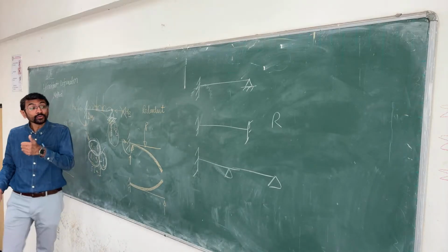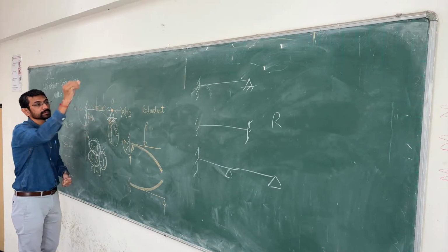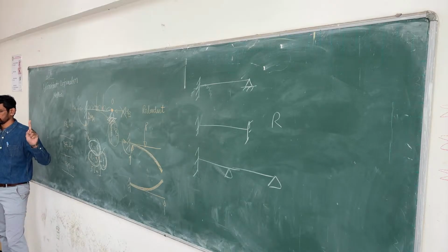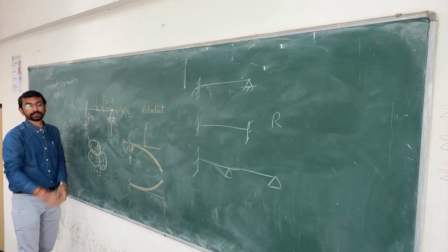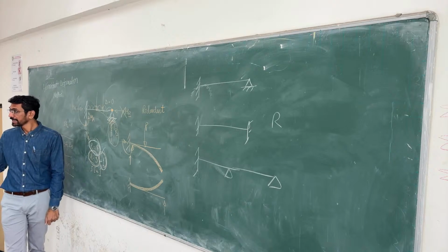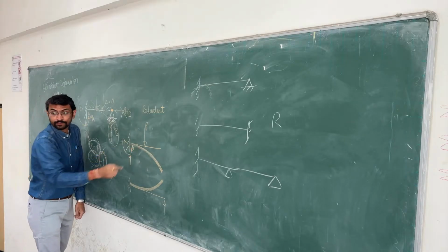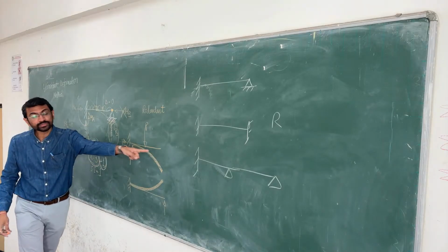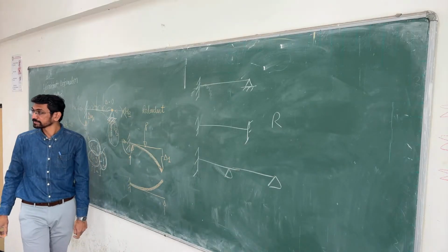It means that you know in this structure that the deflection of this point is 0. True? This point in the structure has zero deflection. Correct? It means that when you are removing it, whatever effect you are getting, you have to nullify that effect. Understand? So you remove the support, calculate this delta 1. True?